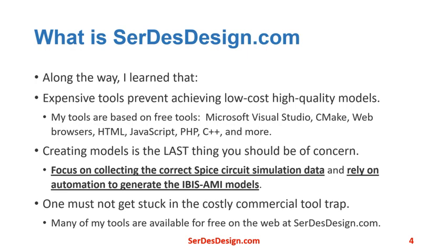My tools are based on free tools: Microsoft Visual Studio, CMake, web browsers, HTML, and more. I learned that creating an IBIS-AMI model should be the last thing you concern yourself with when it comes to creating IBIS-AMI models. Focus on collecting the correct circuit data, and use automation. My tools rely on automation to generate models from measured and simulated circuit data.